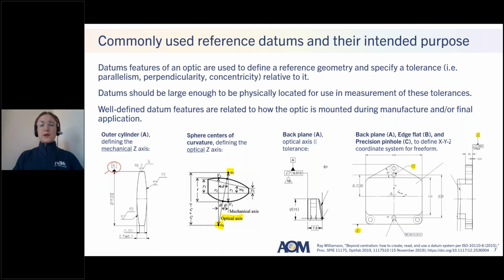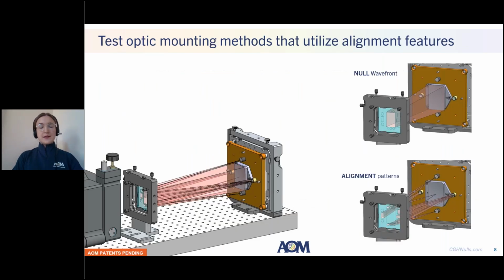So with our test optics, we want to make sure that we have datums called out that are related to how that optic is being mounted. And then when we go to mount our optic in our test, we want to make contact with those datums.